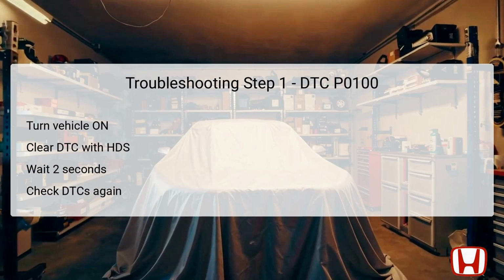After clearing the code, wait for at least 2 seconds to stabilize the system, and then recheck for any pending or confirmed DTCs using the HDS again. If P0100 reappears, it indicates an ongoing issue requiring further investigation.